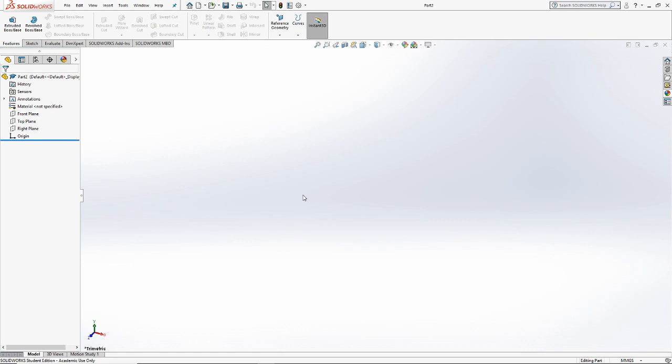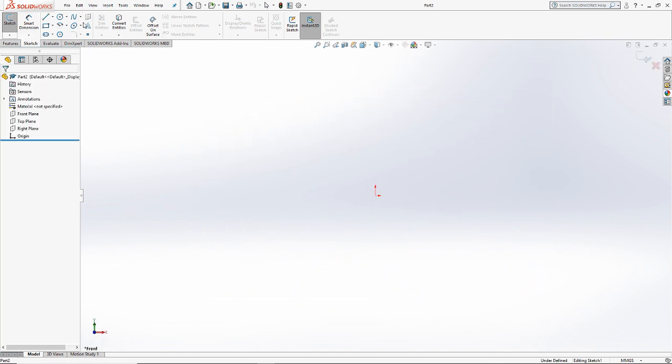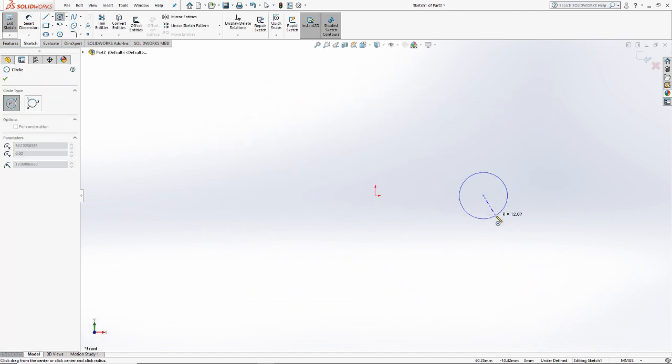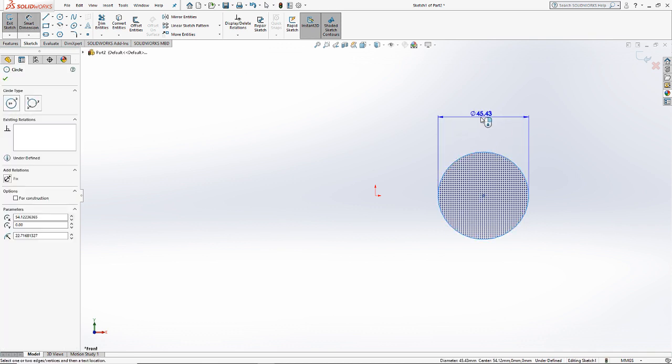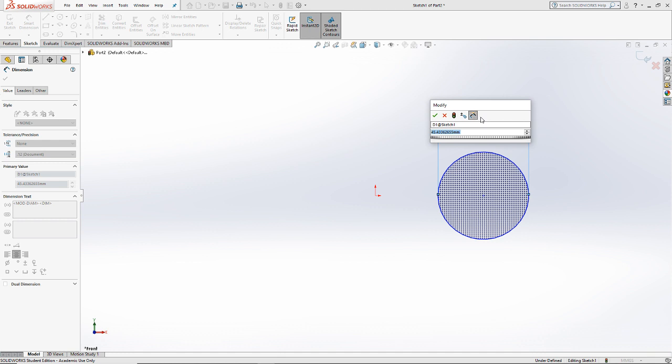But the point is, in order to create this shape, I'm going to go back into the front plane. I'm going to draw a circle. And on this circle, I'm going to have to establish a dimension. We cannot procrastinate forever. What do you want the diameter of that circle to be? 2 inches? 0.5 inches? Do we have enough information on this drawing to know that? We do. How do we figure it out? Yes, we figured it out with geometry.